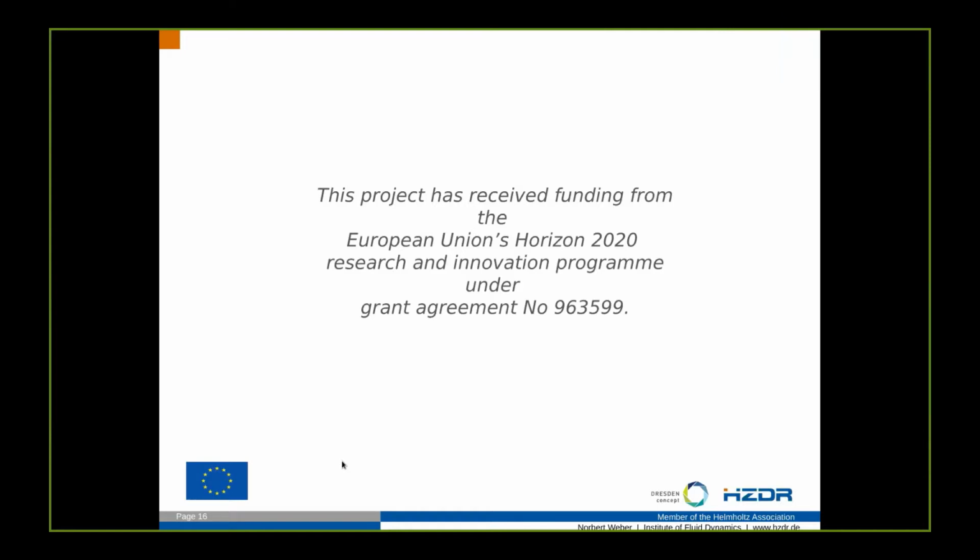I think one good way would be neutron imaging, because with neutron imaging you can see very well the water distribution, or the liquid water distribution, inside the cell. Maybe also with synchrotron, but I'm less sure. And then I would say also that experimentally with a potentiostat you could measure, for example, the local current density, local cell voltage and such things. But I didn't try that honestly.